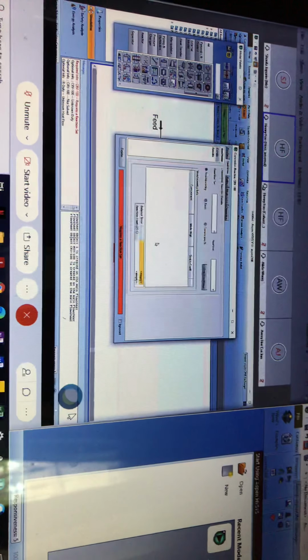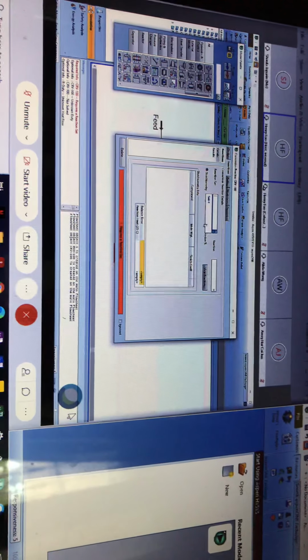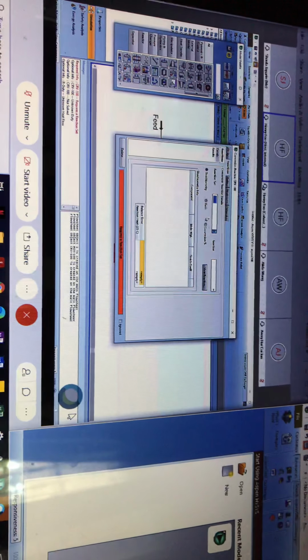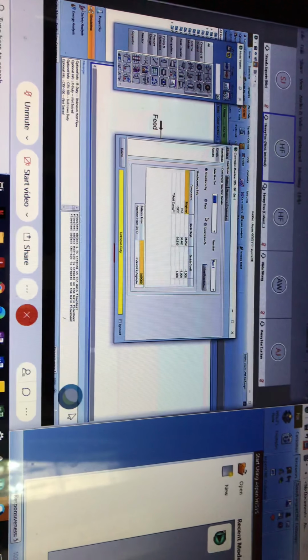So we have yet to define what type of reactions are involved in this reactor. So we can click on the second tab, Reactions. Under reactions, you can scroll down. We are selecting Set 1, since we only have one set of reactions, so there's no other option for you to select.